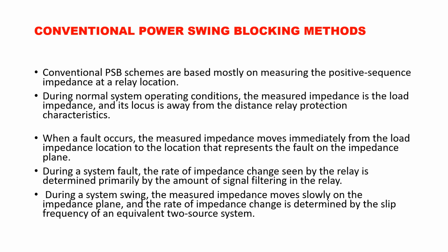So what is the fundamental basis? The fundamental basis I have explained in other lectures also, that it measures the impedance. How does it measure the impedance? It does measure, meaning the relays which are required to give the trip signal in case of a real fault. What do they do? Basically, the distance relays measure the voltage and current. When there is a fault, the voltage collapses or starts reducing and the current starts increasing due to the fault.